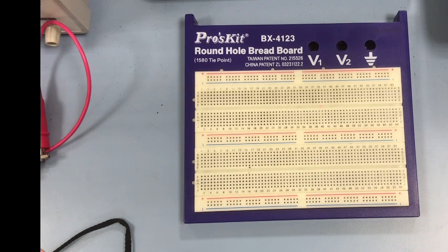So guys, today we will do our first guided lab, which is Ohm's law. Previously I already read to you the experiment procedure. Now we are going to create the circuit based on the schematic diagram. First we will do figure 1.1, measured current for respective voltages and resistance. Basically we are using 100 ohm, 150 ohm and 330 ohm.